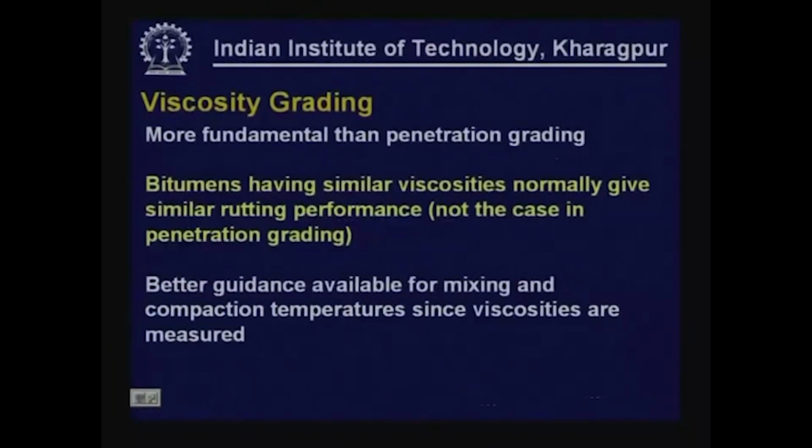So, as I said earlier, two different binders having the same penetration may not reflect similar rutting performance, whereas two different bitumens having similar viscosities more or less will give you similar rutting performance.